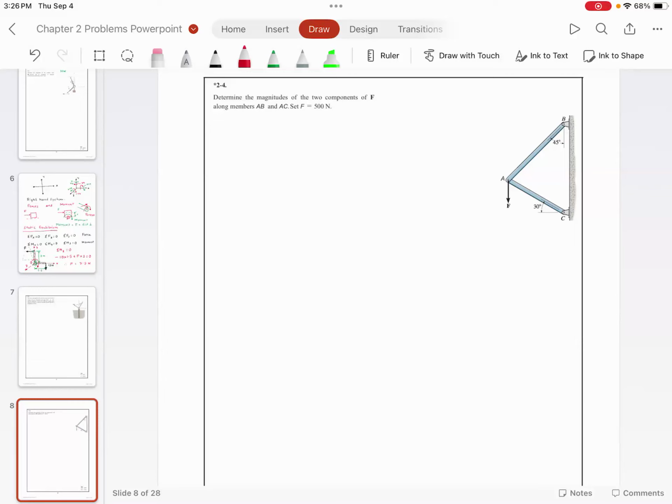So wherever you have elongation, that is called a tensile force. If you are pulling, that is called the tensile force. Whenever you have a member where the forces are going inward, that is called a compressive force. So please try to understand. So let's start with this. We have a tensile force here, and we have a compressive force here. Now, do you agree with me that this entire truss is interconnected? This truss is in equilibrium.